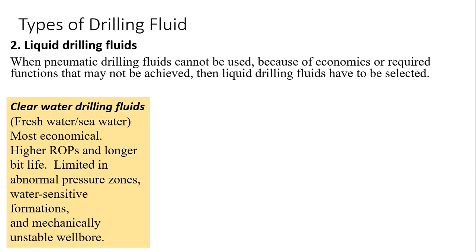But one thing about clear water or normal water is that it is limited in abnormal pressure zones. We have zones that have abnormal pressure, where the pressure may be very high or extremely high. So in our analysis before we drill, we do a pressure sensitivity analysis, so that we know the zones or formations that have abnormal pressures.